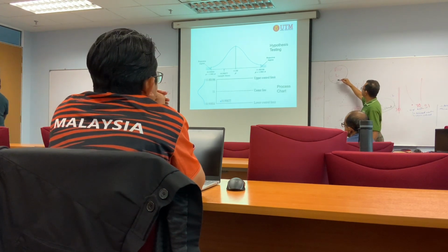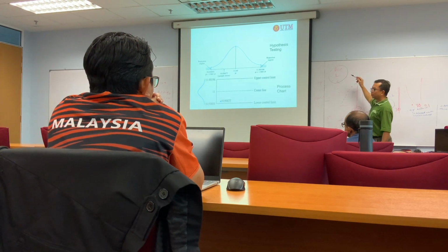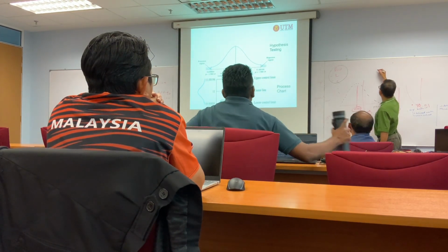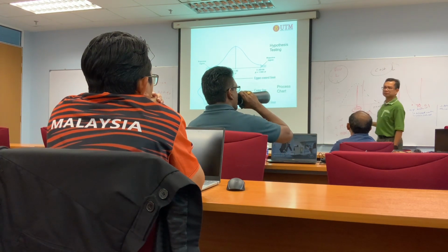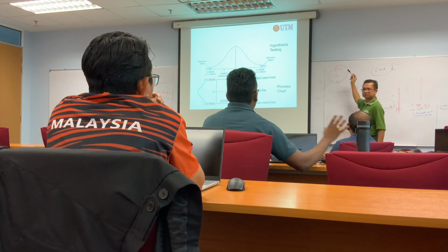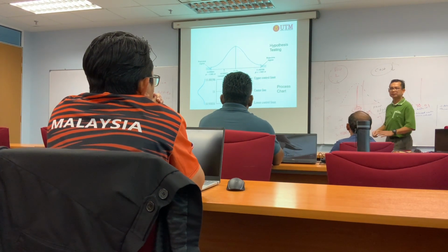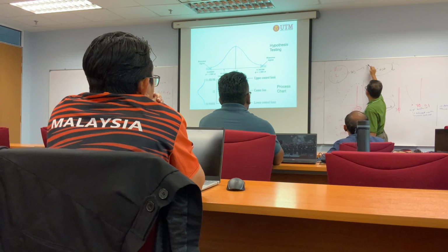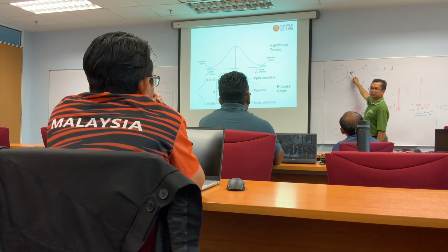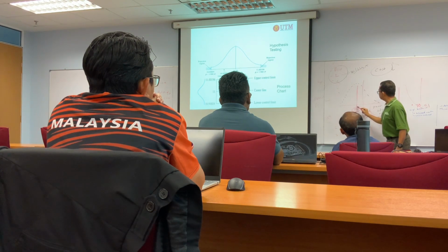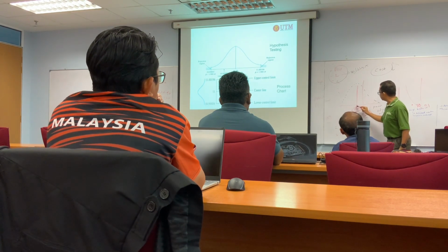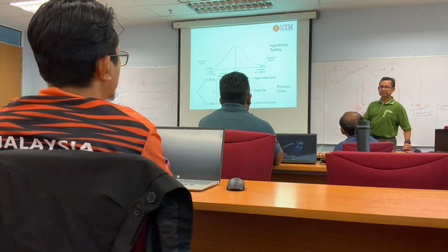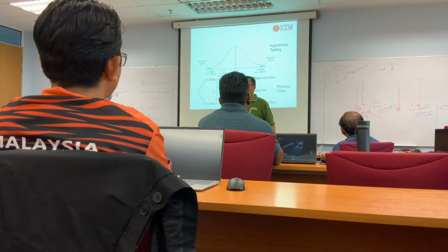So we adjust this parameter so that we can adjust this. But let's say we have 4 parameters that are important, for example. Out of these 4, we can adjust all 4. We adjust one by one. We give priority to the lowest cost. The philosophy is cost. We adjust at the lowest cost. If we feel that length is cheaper than others, we try to adjust length because we have the range for the length, for example. So we adjust the value, whether or not it will shift the mean. If we can get this mean, then we stop. So that's it, done. This is how we do what we call design for quality.